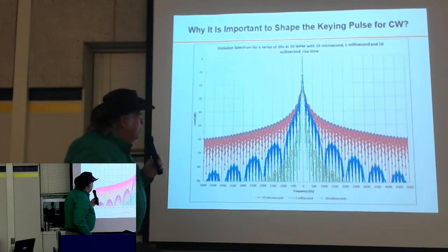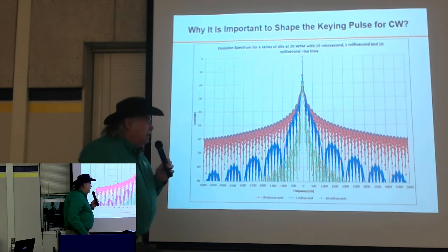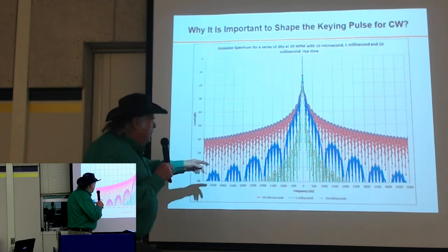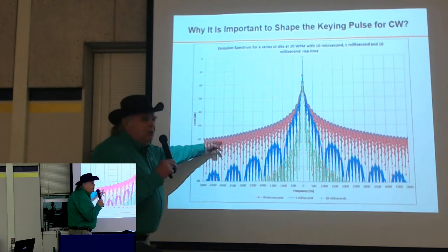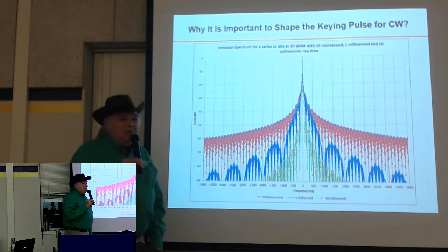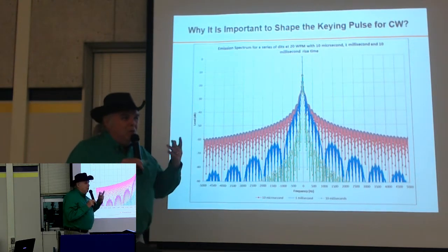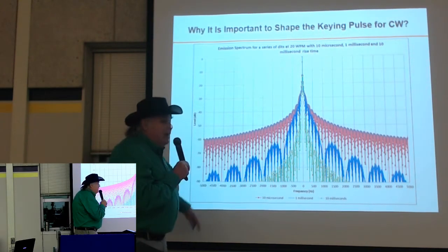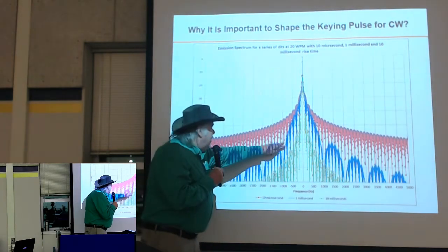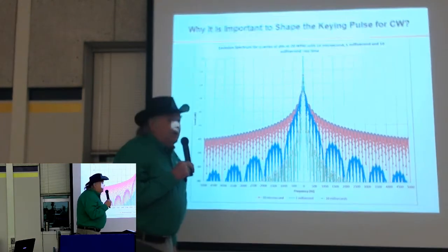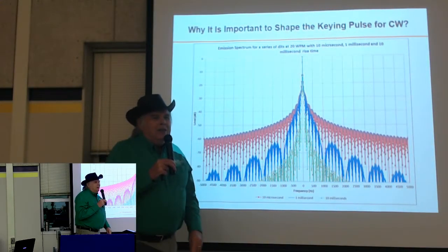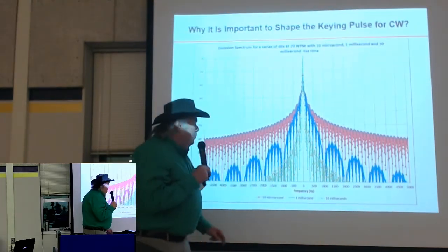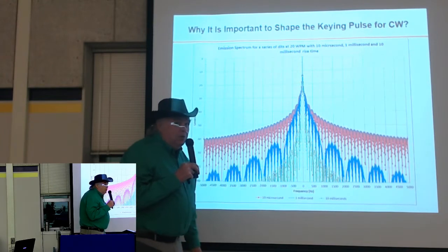So I'm going to look over a little bit wider bandwidth. This time we're looking over plus or minus 5 kilohertz. And you can see a dramatic difference. And this is why people used to get pink tickets from the official observers with their transmitters that didn't have a very sophisticated keying circuit and didn't really do waveform shaping. Because if you'll notice here, 5 kilohertz away, it's like 60 dB down. Yet at a kilohertz away, we're only about 45 dB down with our rather crude directly keyed cathode. Whereas on my shaped keying waveform here, you can see we're way much further down.